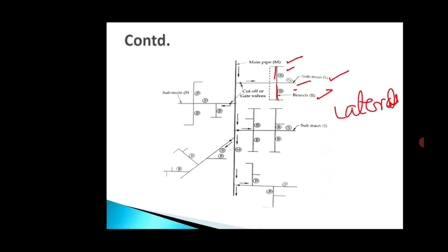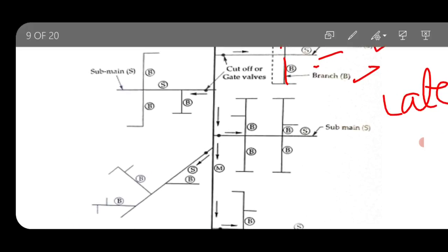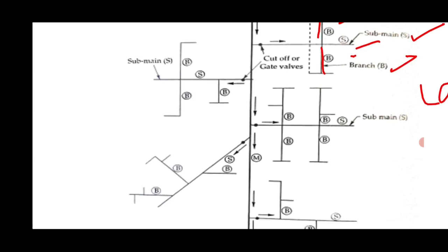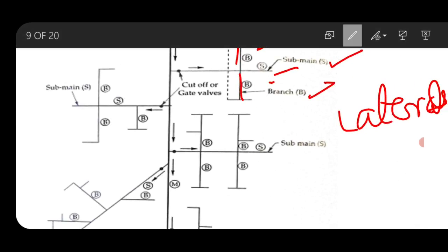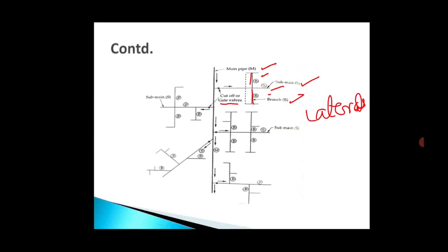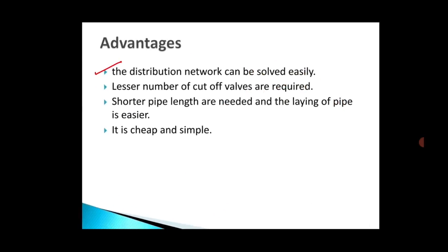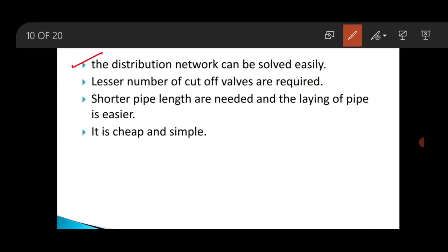So these are the cut-off valves. See here. Here there are fewer cut-off valves used. And shorter pipe lengths are required. And the laying of the pipe is easier. It is cheap, simple and can be extended or expanded easily.